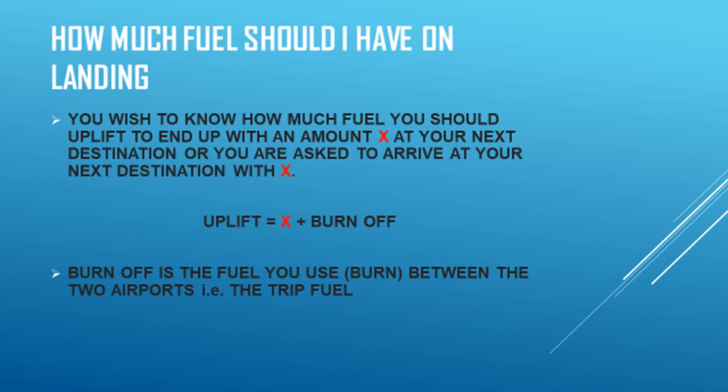If you are told by your operations department that please plan to land with an X amount of fuel at our base station, how would you work out how much you should uplift where you've landed? So let's say airport C is your base.